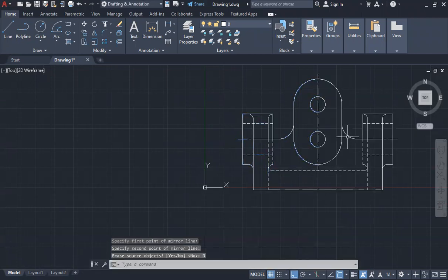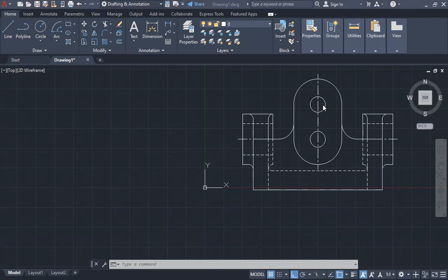No. Okay. So the reason why I changed my line types first, obviously, is because I don't want to have to do that twice. I don't want to have to change property types here and then select so many lines to try and change properties. It's just a way to cut down on my modeling time. But you can use any approach that you'd like. If you would rather draw all the lines and then change all the line types in one shot, then by all means do that.